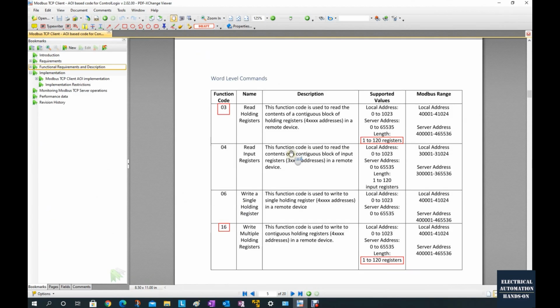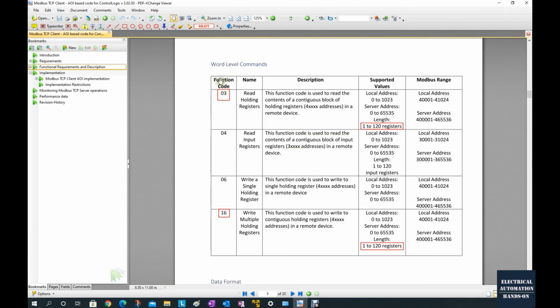And this trans type, as required from the manual, that is the actual function code we need to use. So in this test, we will test 03 and 16. We will type in the 03 and 16 into that trans type. And keep in mind here, if we are using one client, when we activate the 03, the server data will be written into this 40,000 address. But when we try to write the data, it will still use this 40,000 address, writing the data from this area to the server side. So when we use the 03 and the 16, they are sharing this address, this area. So we need to work carefully about this.